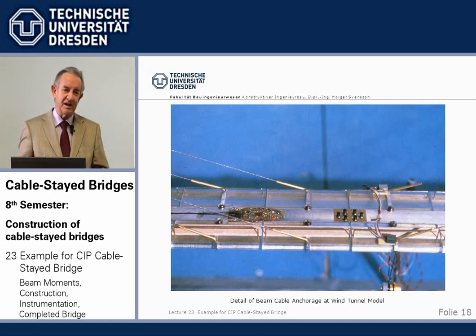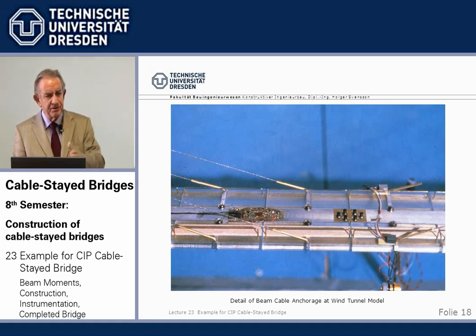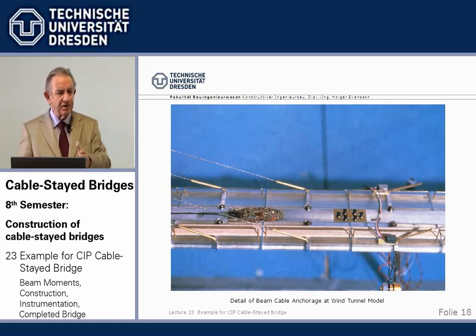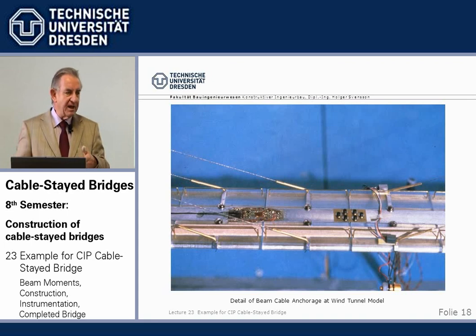For the Helgeland Bridge, it came out that any flutter phenomena would occur only at very much higher wind speeds, and the governing loading for sizing was buffeting, which means the wind which has different velocity, and we have the gusts, they bang against the beam sometimes in period.